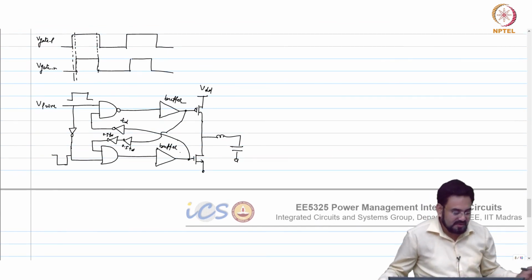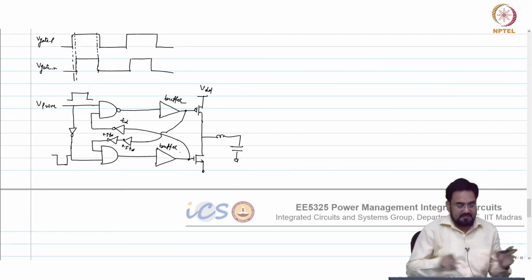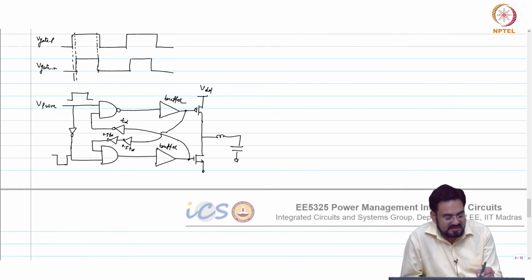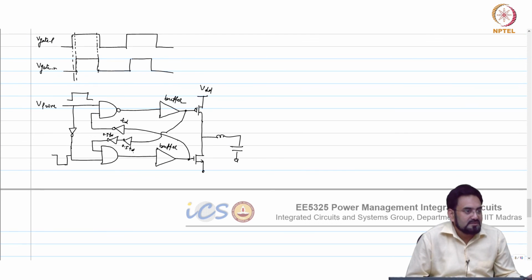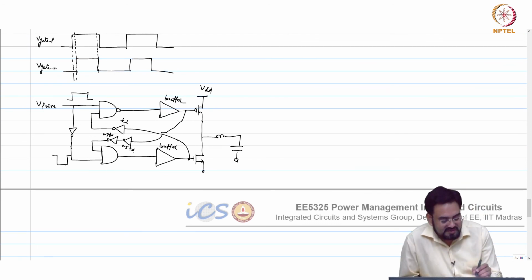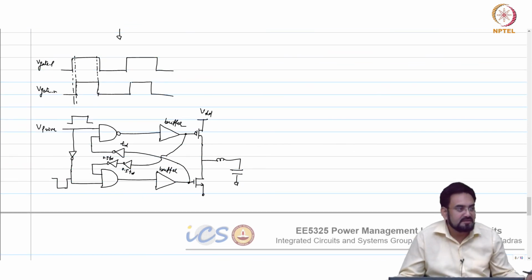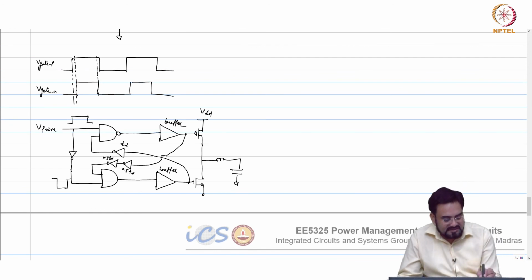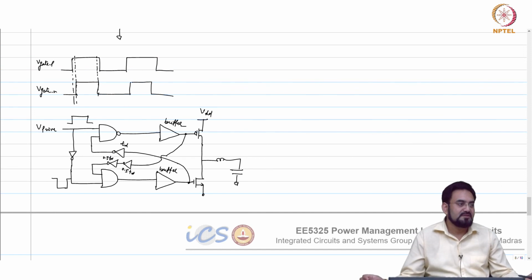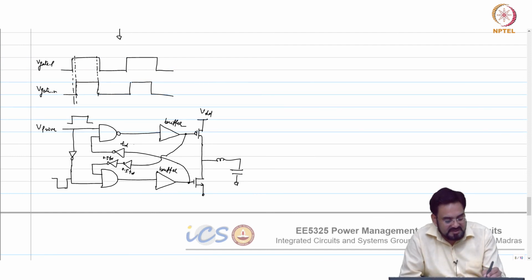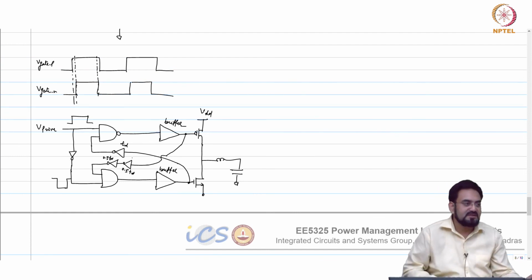So what will be the total delay here, I mean the dead time or non-overlap time, if you ignore the delays of stages before the buffer? One thing you have to remember is that you are measuring the delay from the gate, okay. Which means if there is a delay in this path, most of the contribution in the dead time will be from the rise time of this, okay. But if you are looking from a midpoint, then the major contribution will be from these feedback inverters, TD.